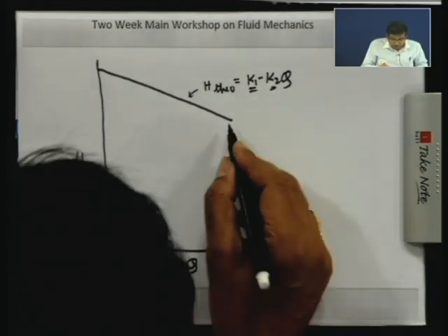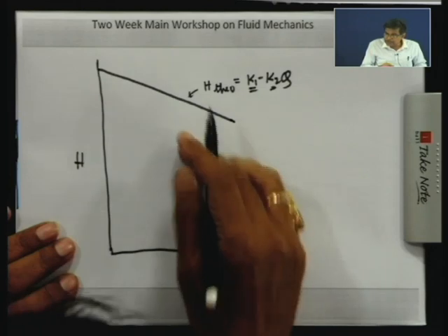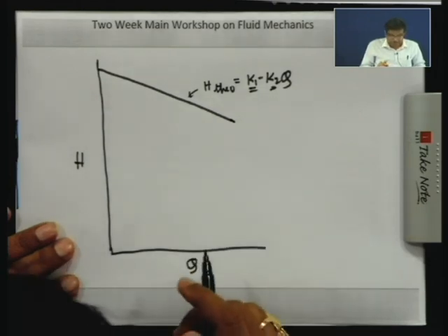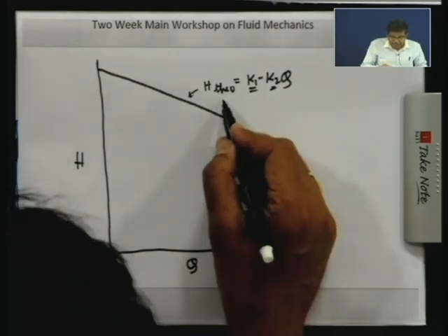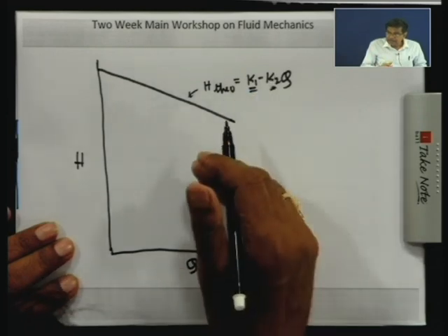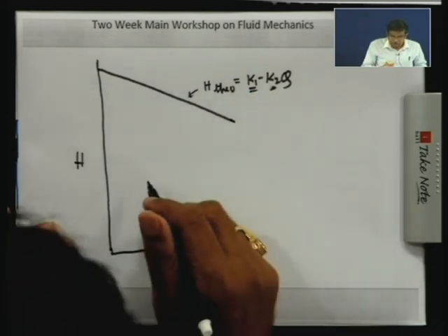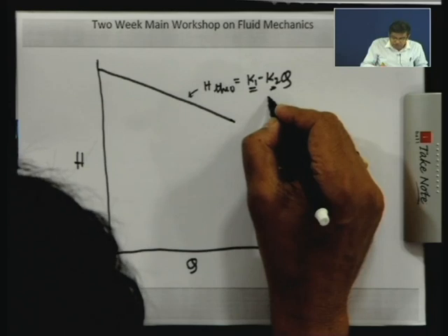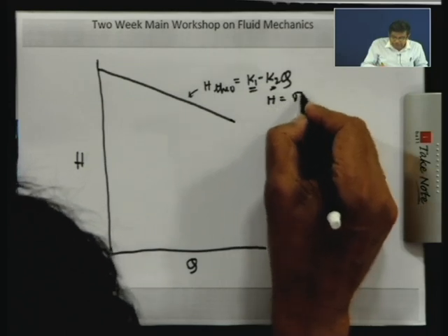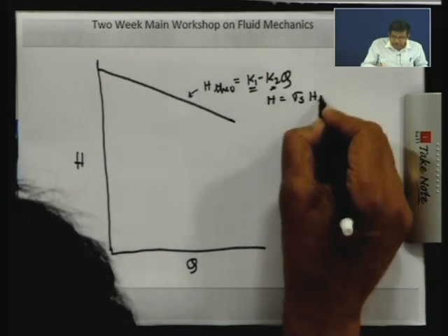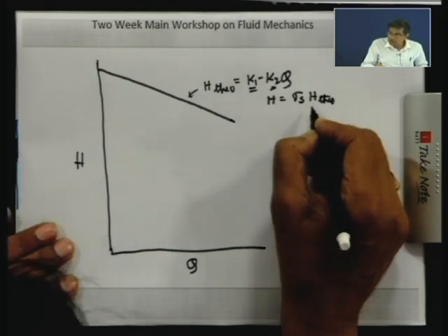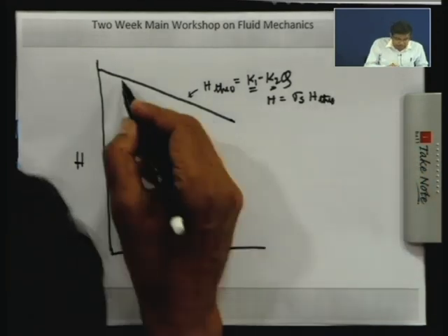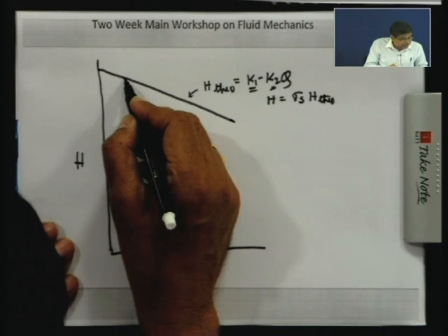Now from this I am going step by step to the actual head discharge characteristics. From here I just deduct the portion responsible for slip, because due to slip H is modified by sigma s into H theory, which is 1 minus sigma s into H theory.